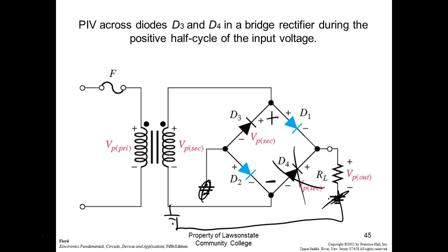The problem is how do you check that thing with an ohm meter? But let's show you how to do that too. So the advantage of this is if one of the diodes goes out, that would be cheaper than replacing 4 of these. For the same ratings, the same breakover voltage and the same current, that is cheaper because they can mass produce those. Here they can mass produce them, but they're doing them one at a time, right?